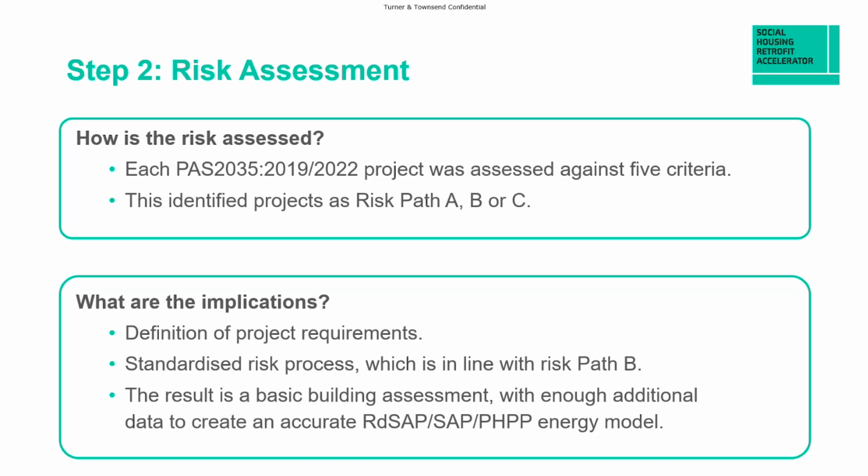It will get you there to an EPC B or maybe an A really quickly. In PHPP, the focus is on looking at the fabric to improve the energy performance of the property before you change the heating or energy producing elements of the property.